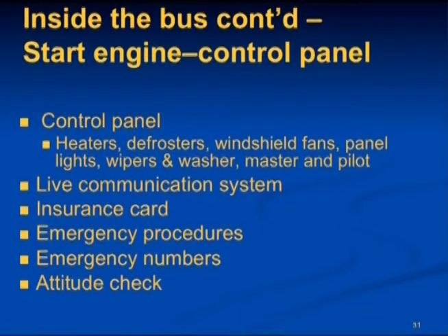Continuing inside, as you're sitting in the driver's seat, now you've started the engine and we're going to check the control panel. The control panel for most buses is immediately to the left of the driver as they're sitting in their seat. The following should be checked for proper operation, adjustments, or conditions. The heaters, the defrosters, and the fan should all operate properly.